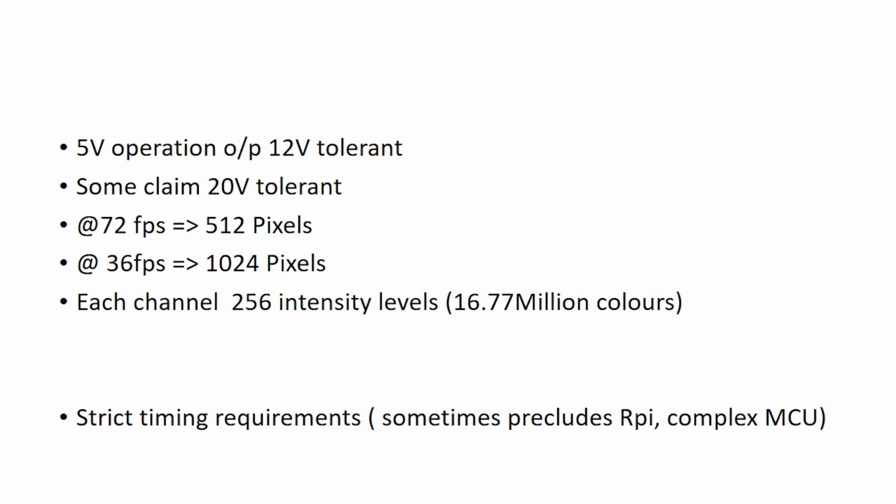Although if I had 18 volts for a DCC, for example, you might want to rectify that and use it as a supply for these because they take a bit of current. If you think about it, each of these LEDs can take up to 20 milliamps. So that's 60 milliamps per NeoPixel. If you get 15 of those, that's an amp. So these things can draw a bit of juice, so you have to be a wee bit aware of that.